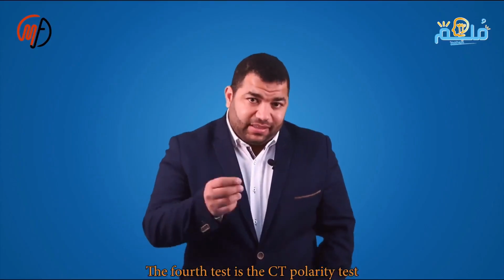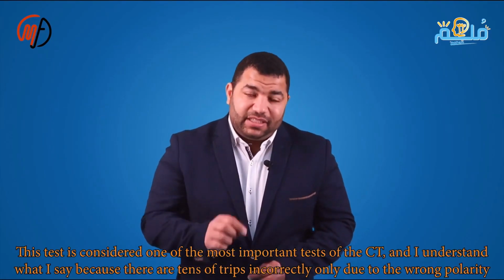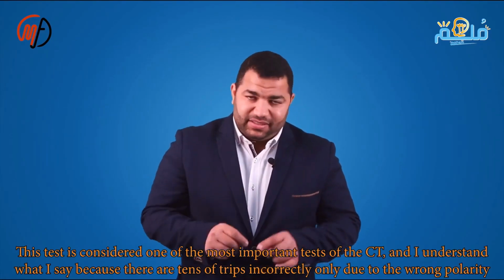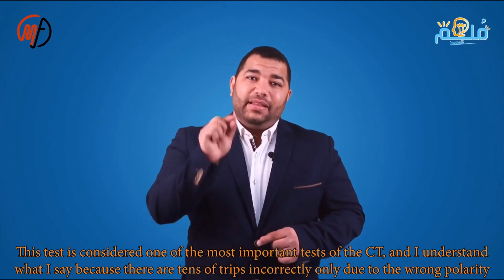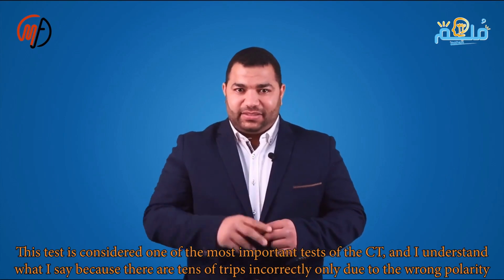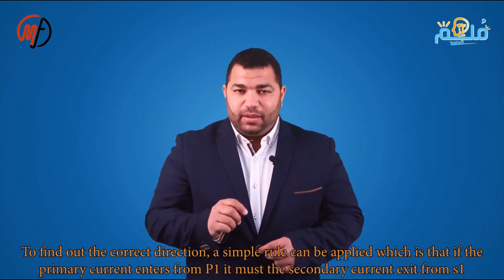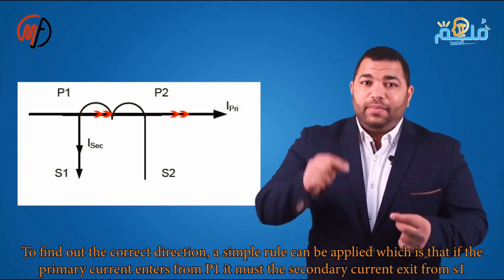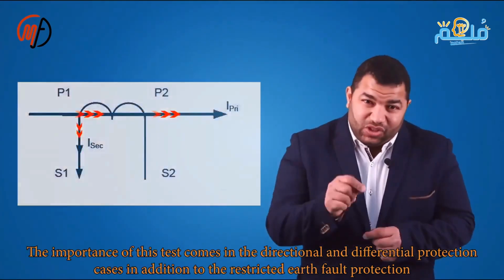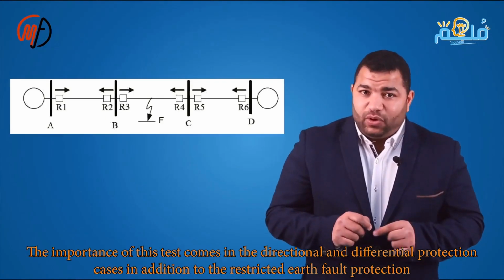The fourth test is the CT polarity test, and this test is considered one of the most important CT tests. I can confidently say that dozens of failures have occurred in stations just because of incorrect CT polarity. In this test, the direction of current flow in the CT is examined, and a simple rule can be applied. If the current enters from P1, it should exit from S1. The importance of this test lies in directional protection, differential protection, and restricted earth fault.